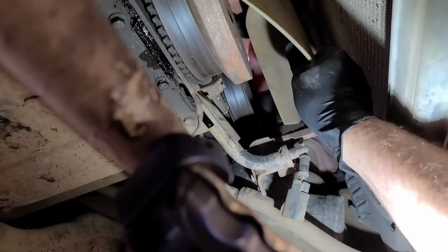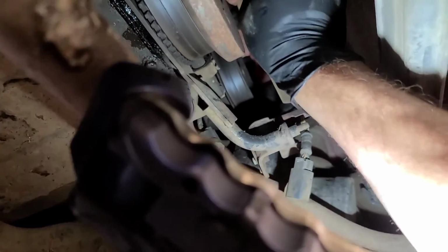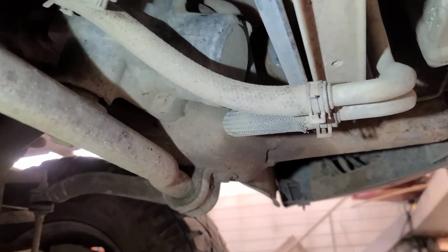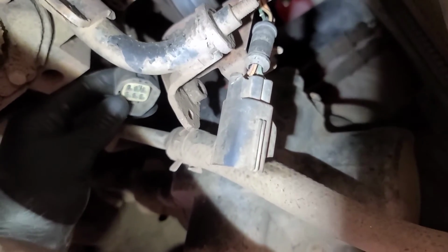It's unplugged. But I noticed the fan blade is completely locked. So either the fan hub is seized, but nevertheless it needs a new fan clutch. Chances are now these terminals in here are compromised because they've been left exposed to the elements. Yeah, they look pretty rough. This one doesn't matter, you're going to get it with the fan hub. But this one here, probably going to need terminal repairs in there because of that.